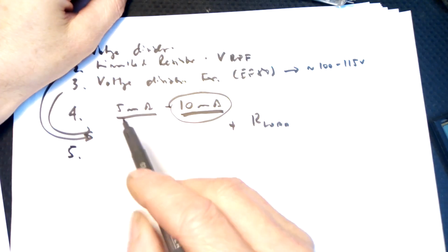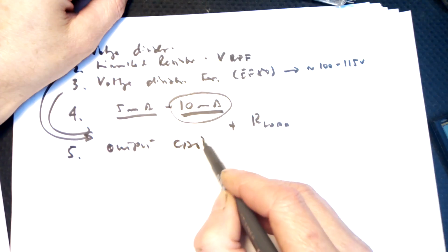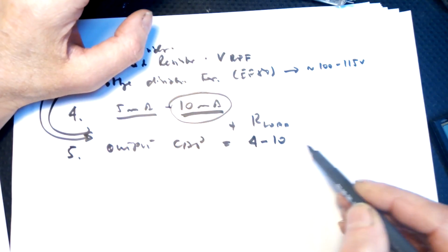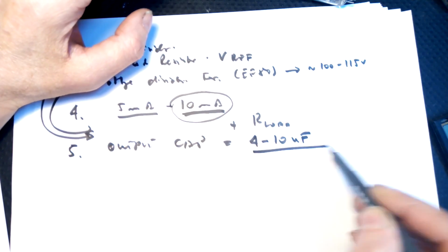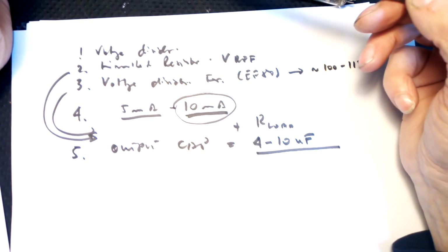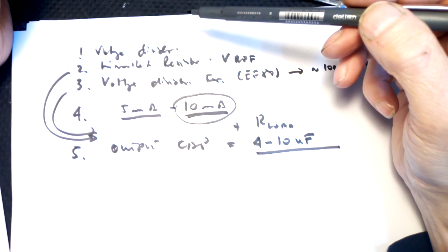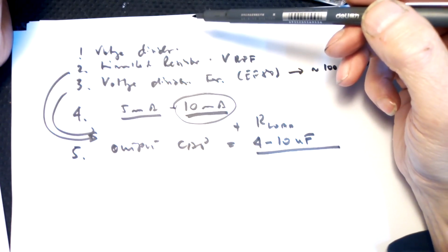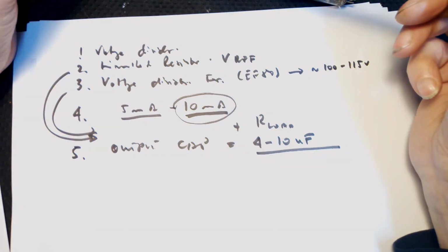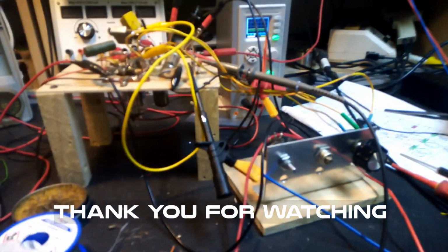Fifth, the output cap, something between 4 to 10 microfarads. This is the maximum. For the rest you can follow this diagram which I included in the earlier, previous video. It's proven, it works, so that's it.